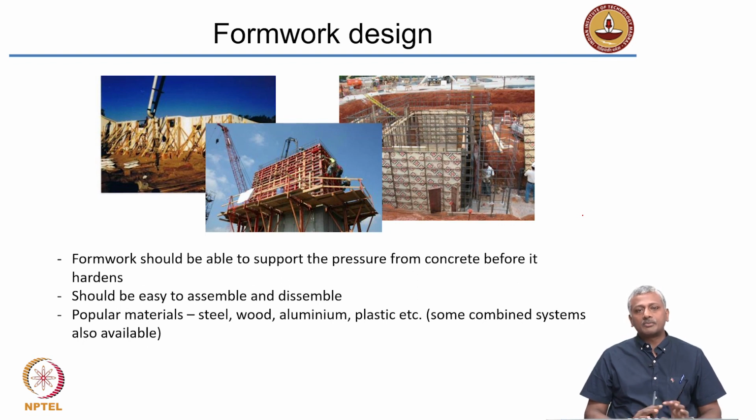We do not really worry too much about curved sections, but indeed there are several examples of construction where curved sections are also used. So, in such cases, you need to design the formwork appropriately with the right blend of materials. Okay? There are different formwork materials. In most of the job sites, you may see that the formwork materials are made out of plywood or other pieces of timber. Okay? So, in such cases, of course, you can imagine that the reuse is going to be limited when you use timber formwork, for instance.